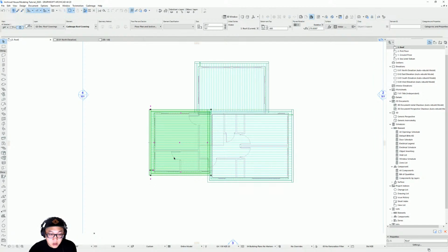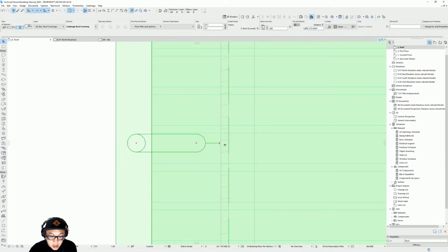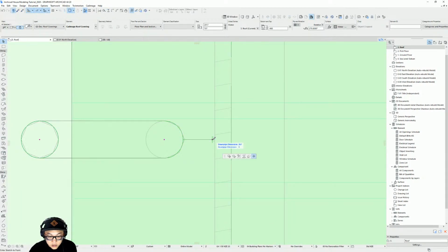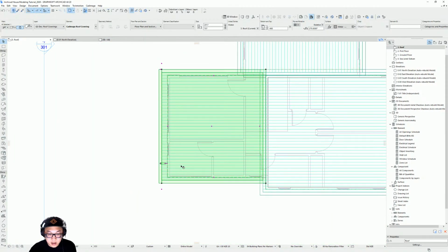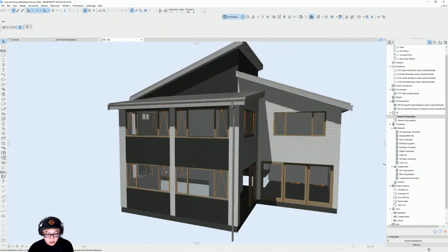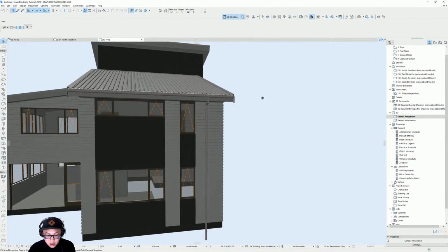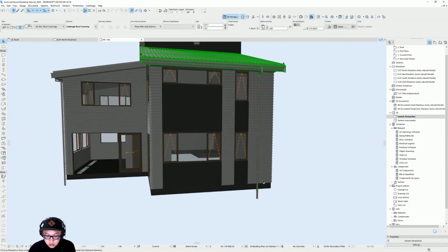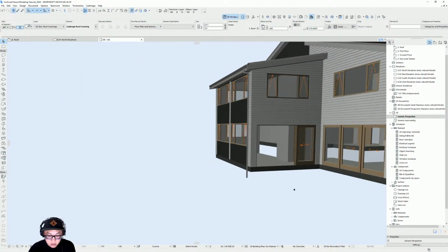of the roof cladding, you can actually move the downpipe position. And here it's actually not touching the cladding, so I can just stretch it so it touches. Yep, it was lagging a little bit. So go back into 3D and it moves a bit. You can also get it in 3D here at the bottom. Shift it up.